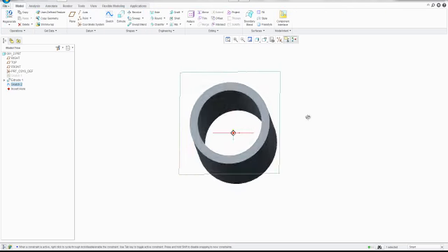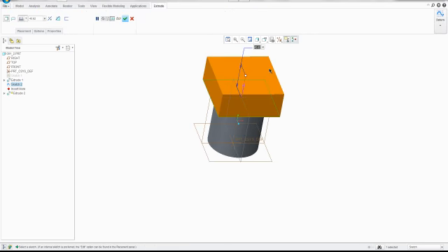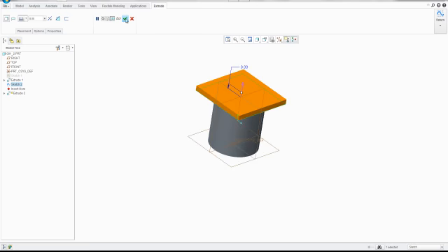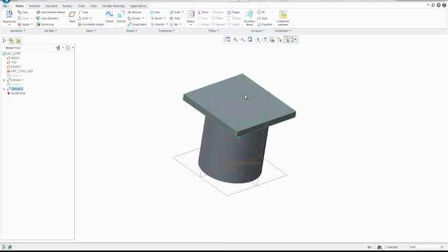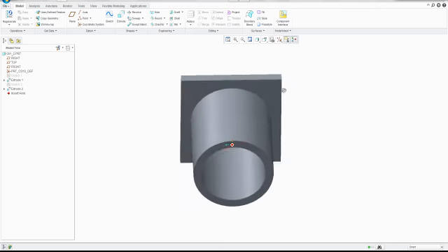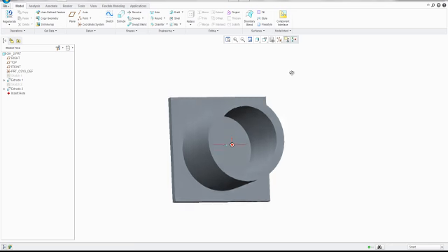So I'm going to select OK, move on to my extrude command to define a thickness. Let's use 8. I think that looks pretty good. Okay, so one thing I can do here is I can go on to create a cylinder to remove material, because notice that I still want the center of my part to be empty space.